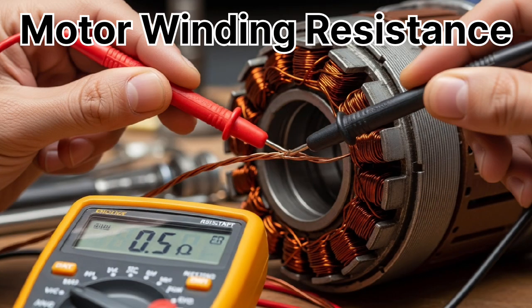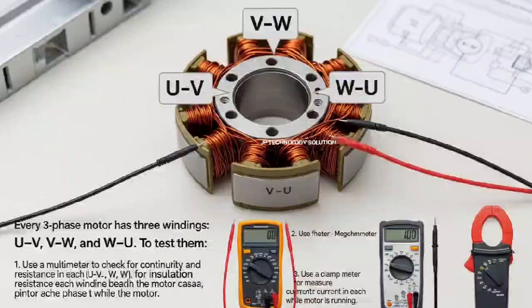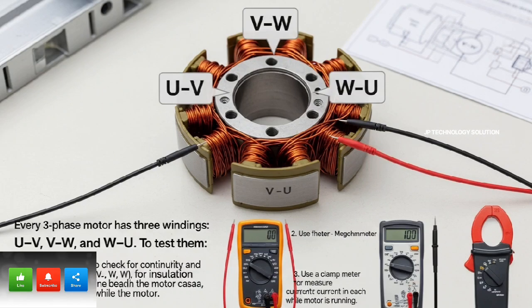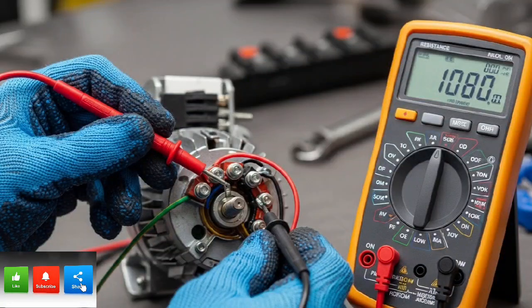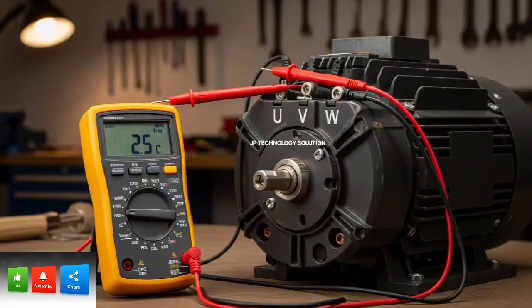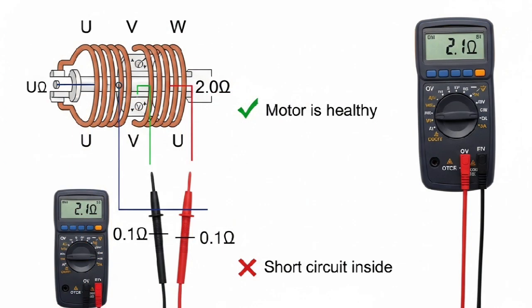Question 23. How to check motor winding resistance? Every three-phase motor has 3 windings: UV, VW, and WU. To test them, disconnect the motor from supply. Use a multimeter in ohm mode. Measure resistance between UV, VW, and WU. If all readings are equal, the winding is healthy. If one reading is very high or infinite, that winding is open. If one reading is very low compared to others, the winding may be shorted.